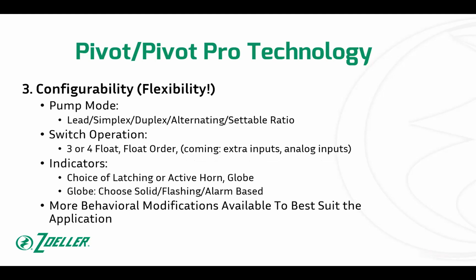The configurability of the panel is huge. This is a big deal. It makes these very flexible. We set them by default to a list of defaults, but if somebody needs it to be a 4 float instead of the 3 float default, they can do that. If they need the float order to be stop lead high lag instead of stop lead lag lag high, for example, you can change the float order.